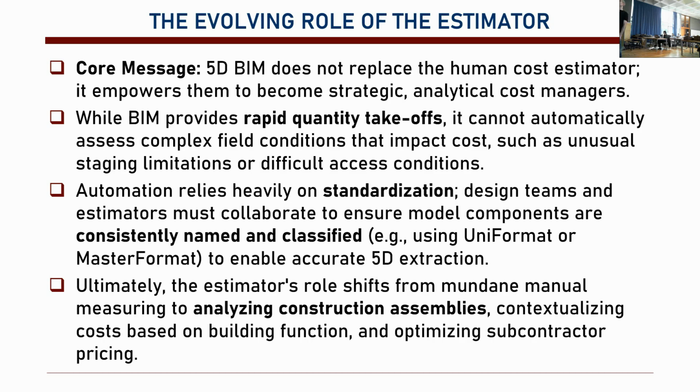One of the most important things is standardization. For that, you have to have consistently named and classified elements in your project. What is a classification? Element classification. We have something called Uniformat or MasterFormat. Uniformat is British, I guess. MasterFormat is American. Basically, a hierarchical classification, categorization of building components.